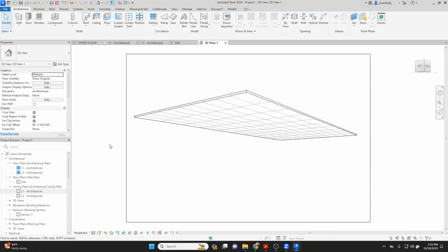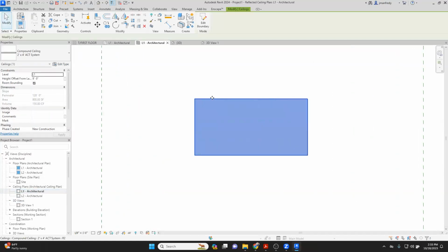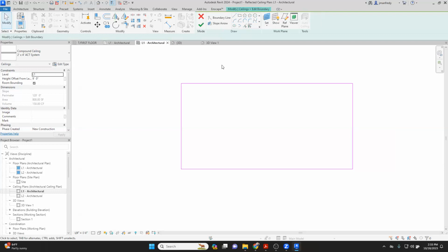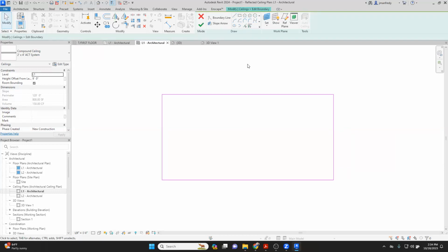Okay, so you can make ceilings slope. Yeah, I'll answer that question in a second. If you want to make a ceiling slope, you can. So I can go to the ceiling plan here. You click on the ceiling and you go edit boundary. You don't have the tools that we had last week on adjusting sub-elements. Like I can't grab this corner and lift it up off the ground, and I can't grab this edge. I can't add points to the ceiling to adjust their heights. So I'm kind of out of luck in that regard.